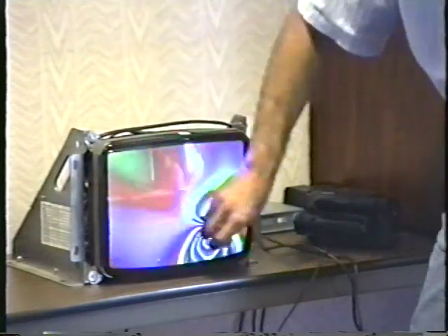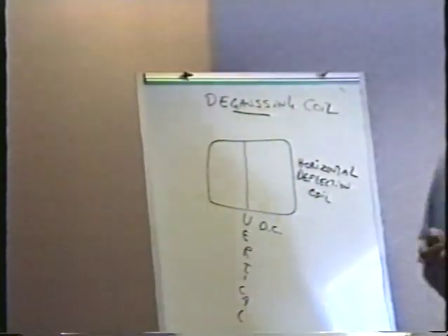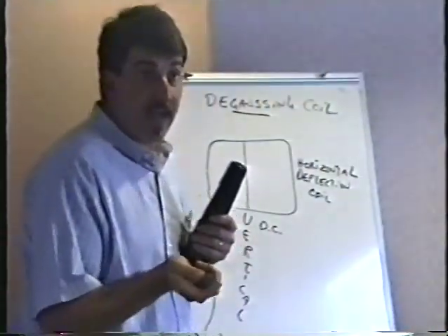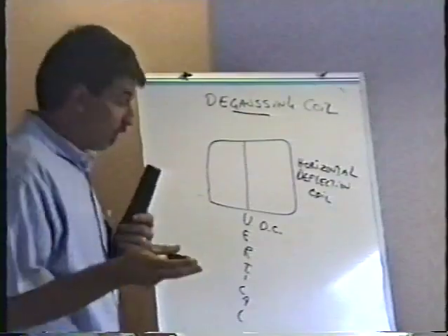But the deal is, I can also kind of do it with permanent magnets. If I take these things in my hand and kind of do that, I can get rid of it that way too. All you're looking for is a changing magnetic field. You just have to scramble up the particles that are magnetized on it. So if you have this problem, you could try degaussing the picture tube, and it usually works.